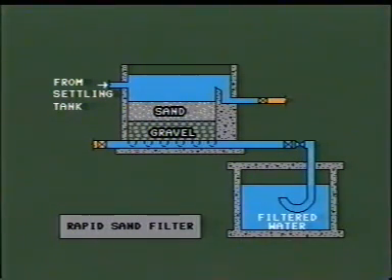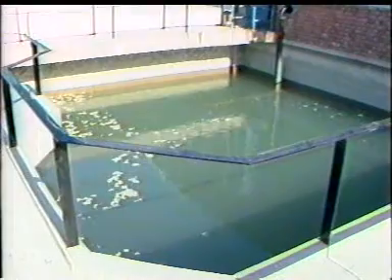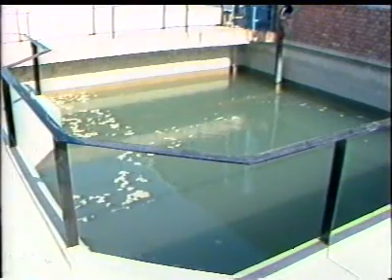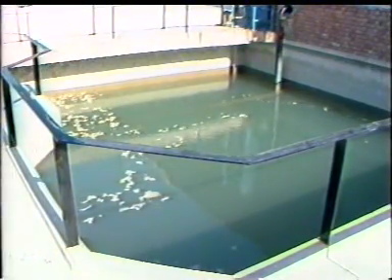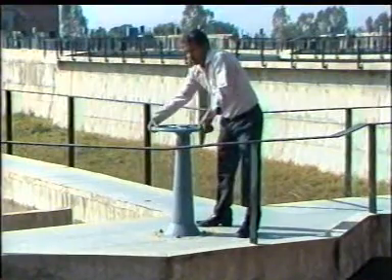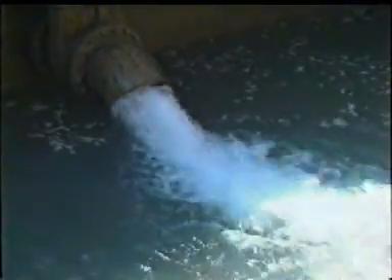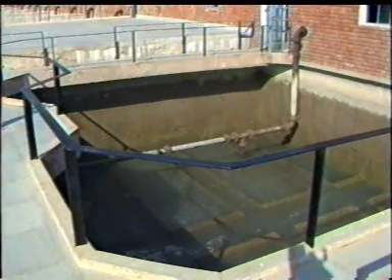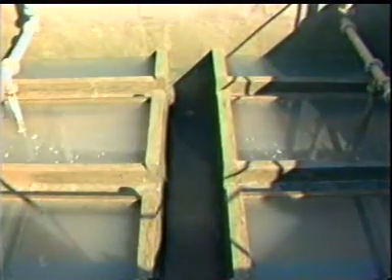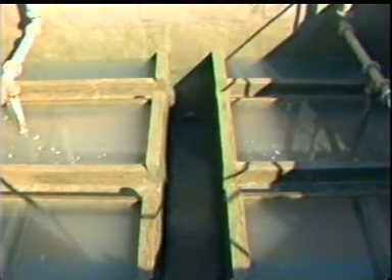During filtration, water passes through beds of fine granular material such as sand, gravel, etc., and gets purified. The filtering media get clogged after 24 to 48 hours in use. It can be cleaned by backwashing. Before starting the process of backwashing, the entry of water to the filter unit is closed. Water in the tank is drained off by opening the valve of the drainage pipe.